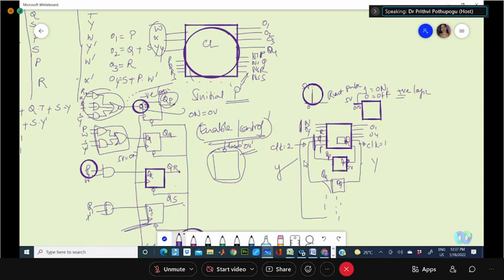Got this? Yes, ma'am. In the present clock, you are defining P. This will be your next state. And along with the conditions, here you have test variables. Now, the test variable value will decide whether from this present state of P it should go to Q or it should go to R. That's why we are taking a combination of the condition and the state together. It will decide what should be the next state.